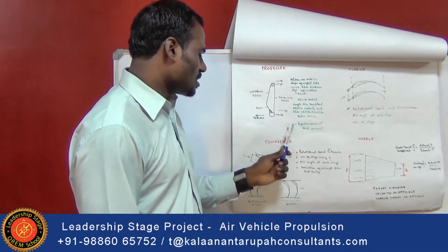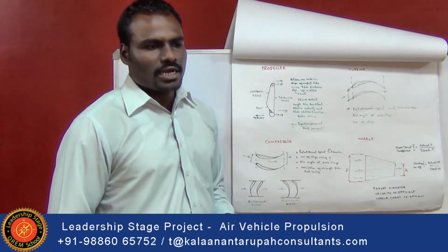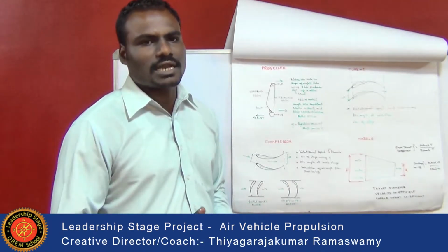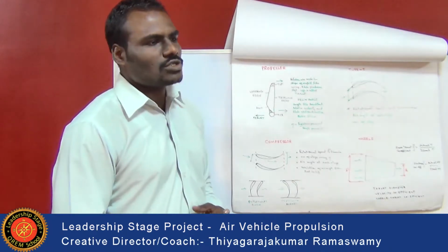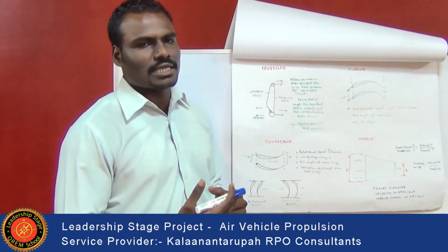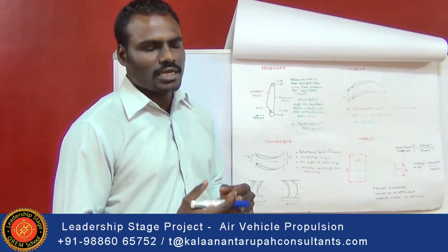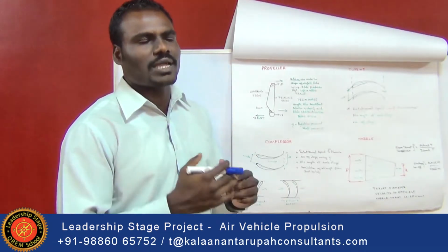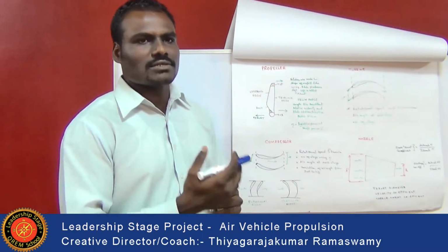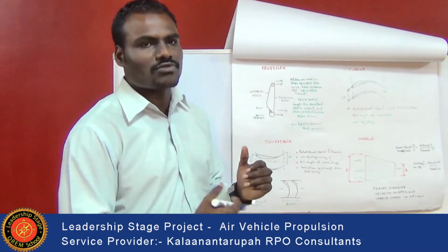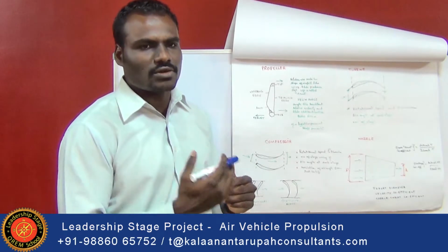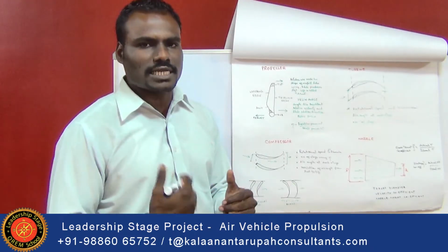The next major part is the compressor, where the pressure and the temperature of the inlet air is being increased and it is being subjected to the combustion chamber. So, the main factors in order to design the compressor: each compressor consists of many stages of blades, many rows of blades. Some of the blades may be rotational type, and some other stationary type.